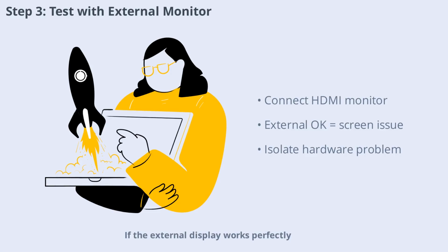If the external display works perfectly while your laptop screen continues to flicker, the problem is likely with your laptop's screen or its internal connections, not the graphics card. This test helps you determine whether the issue is hardware or software related.